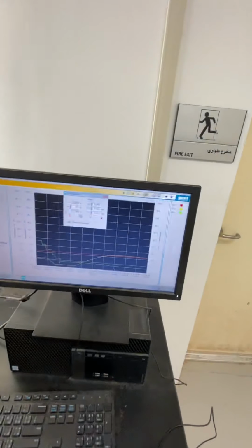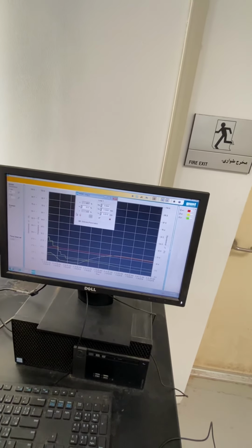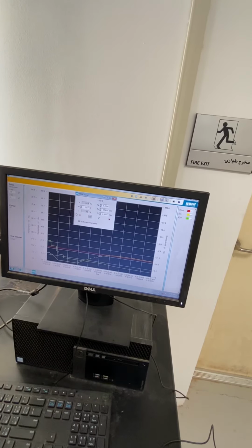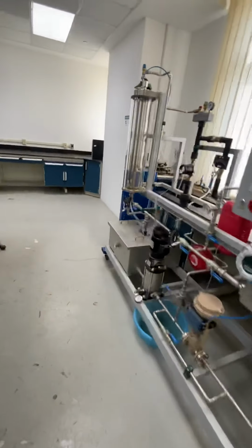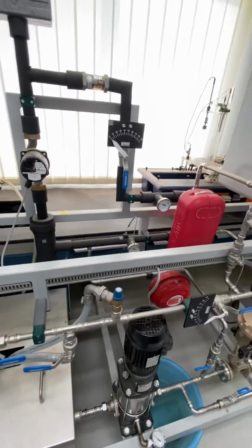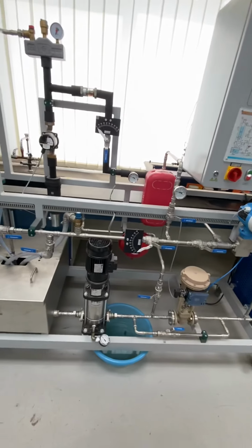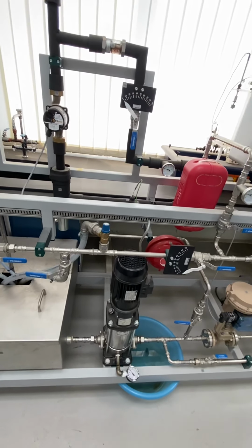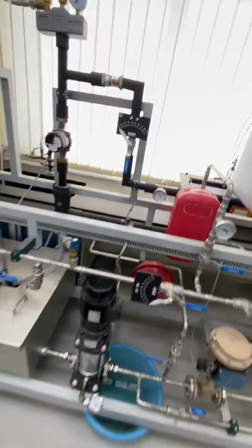Okay, and I'm going to show you one of the biggest and most difficult problems to be detected in chemical processes, guys, which is basically the fact that some of the pressure safety valves, this is the pressure safety valve we have in here, might get stuck open. Now we all know that the pressure safety valve is used to prevent overpressure in the system.